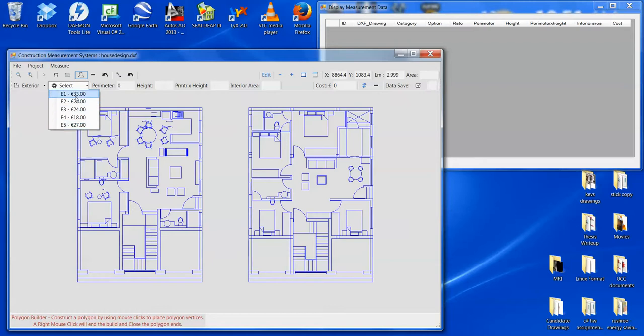There are other options. I haven't hard coded every option in, so just the main options. These would be everyday options for houses. And the same with interior walls. I have 6 options for interior walls. Again, the most common, 12.5mm standard plasterboard dab fixed to blockwork, skim finished.